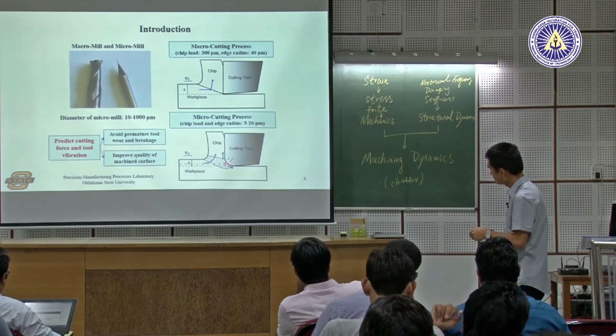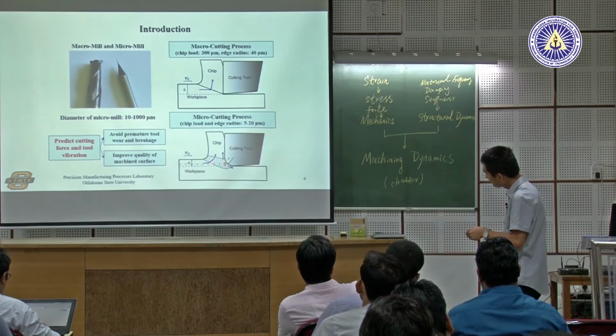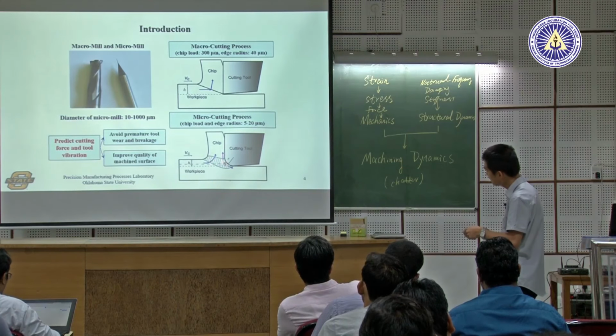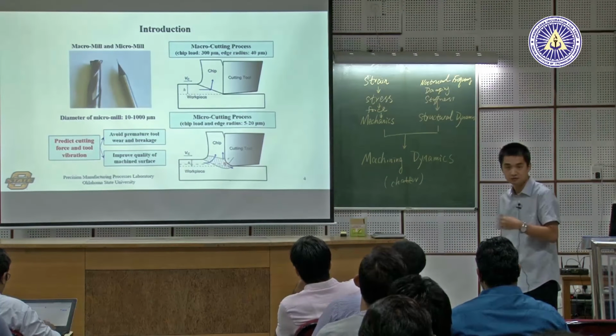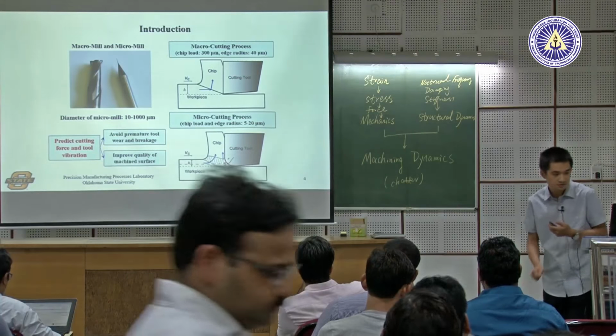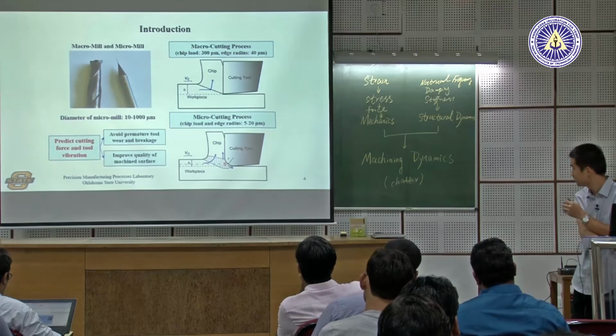Then we have to define a stagnation point where the upper part of the material forms the chip, but below that it forms the surface finish, which is more like the plowing effect. And above that, we know from previous sessions, it's called the shearing phenomenon, right? That's a major difference from the fundamental aspect when analyzing the difference between micro and conventional machining.